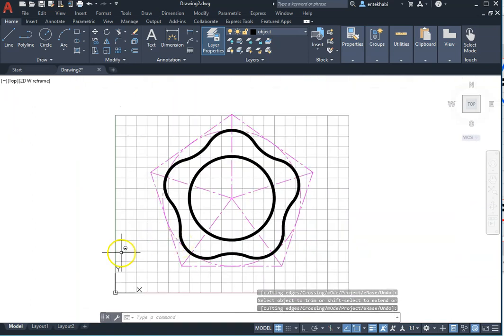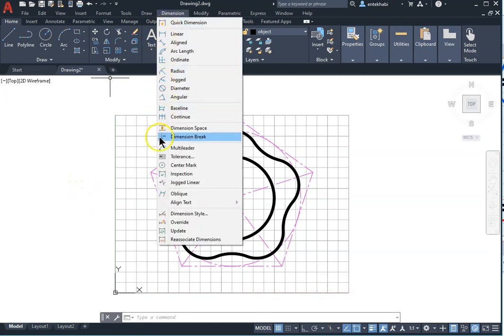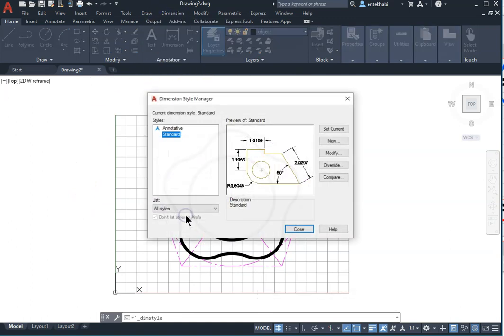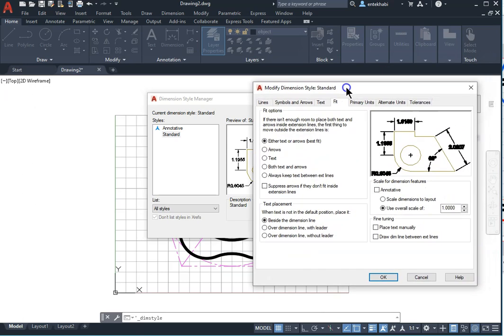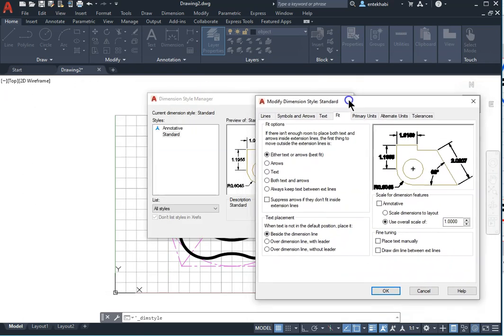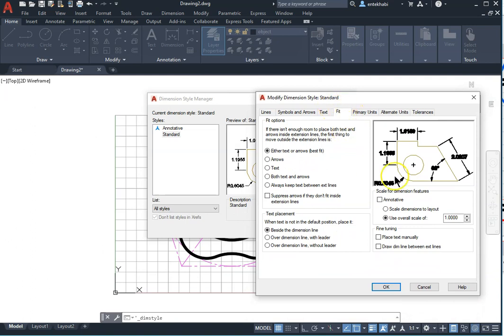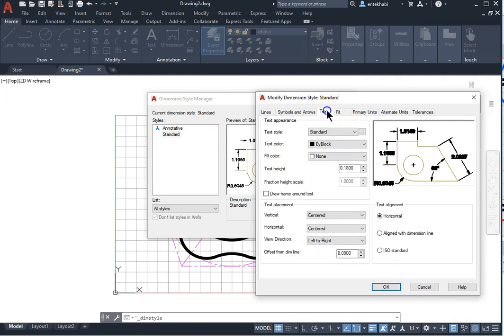There's an extra polygon, we can erase that later on. First, set the dimension style. The one that we are using for mechanical drawings, most standards are 0.125 for text size. For overall scale, fit, dim scale is 1 because the scale is going to be 1:1.